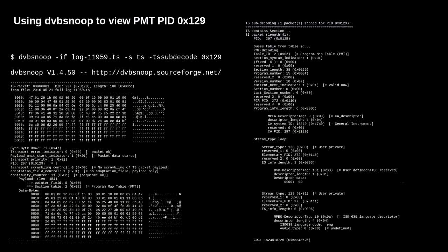With the satellite and cable interfaces, DVB Snoop can be used to view a lot of information about the transport stream. It's enough information to be quite overwhelming. So the trick to using it is being able to sift through the output for the relevant information. DVB Snoop also doesn't recognize all of the DigiCypher 2 tables because it's a non-standard system, and DVB Snoop is targeted towards the standard systems. So DVB Snoop may not be able to tell you everything about the transport stream, but it was still a very useful tool for all the information that it can provide.